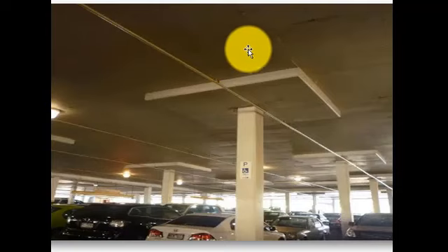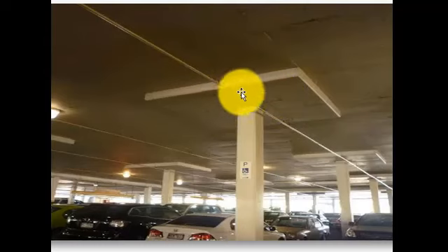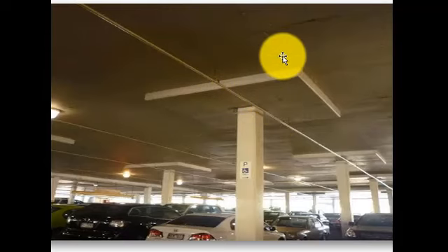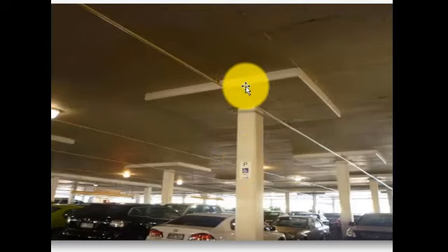So if you look at it here, at this point, you can see it is part of the slab, but it increases in depth, then it comes down. So it means that at this point over the column, the slab has increased, the slab has dropped, the panel has dropped. Do you understand? So it is a dropping panel flat slab. It is not just easy to connect your column straight with your slab. There should be something. So it has to be a dropping panel, or it should be a column capital.